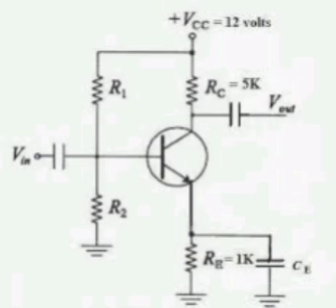Core construction: both transformers and induction machines have a magnetic core made of laminated sheets of silicon steel. This core helps to guide and enhance the magnetic flux and reduces eddy current losses. Windings: transformers have primary and secondary windings, while induction machines have stator and rotor windings. These windings are essential for the induction process in both devices.